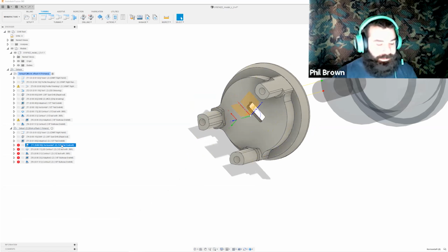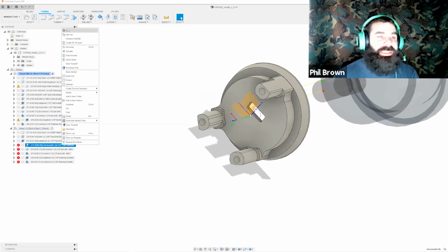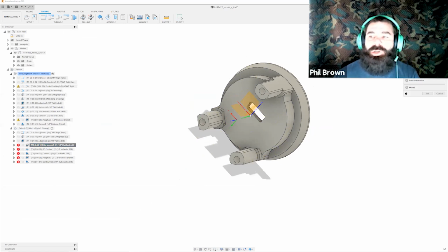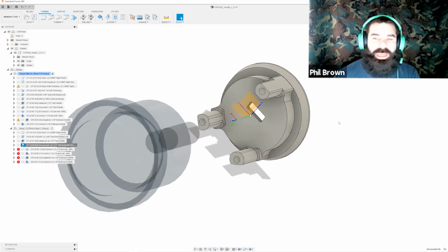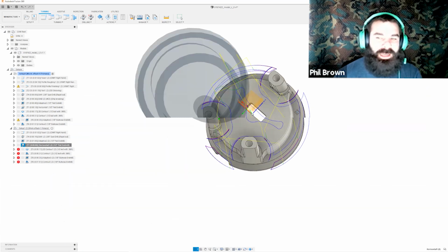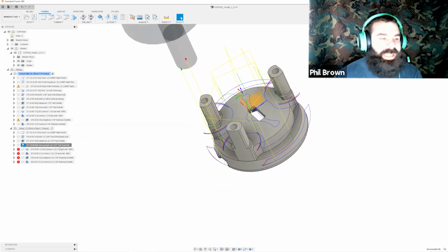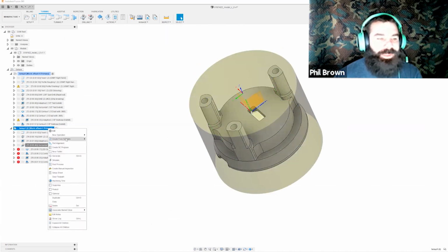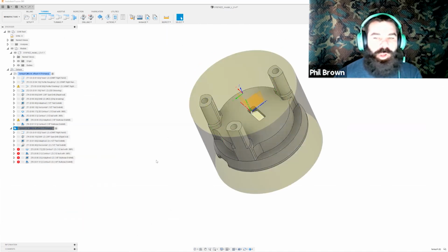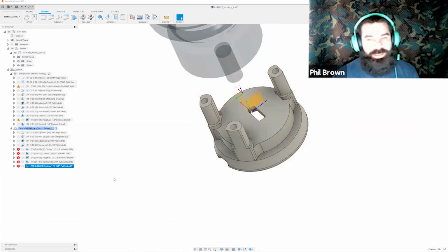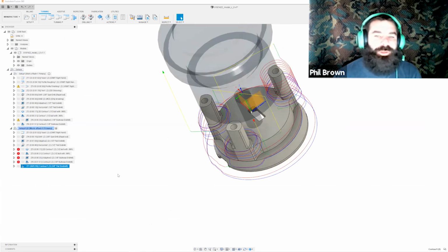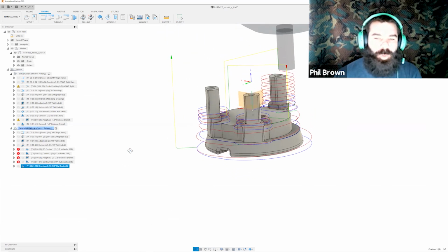Ideally, the horizontal, a great tool path again that I'm going to steal. This time we'll go ahead and turn off our silhouette. I'm going to just say no boundary and hit OK. And what you're going to see is it's going to actually clean up all those flat surfaces around my part. Lastly, I do have another template here that I could steal. This one I call my 2D contour. What this guy is going to do is actually find all the vertical walls here and clean up those walls.